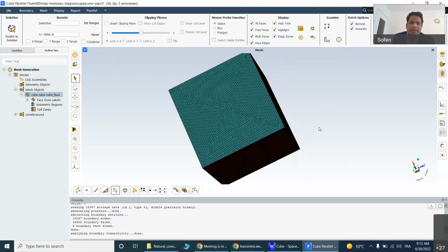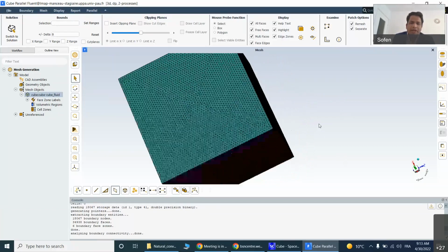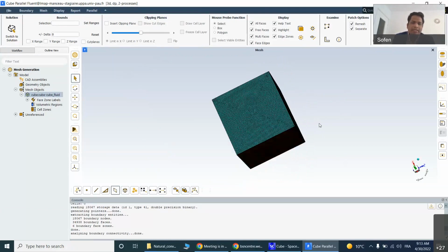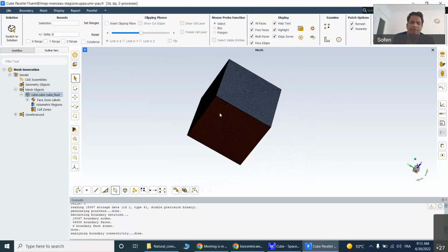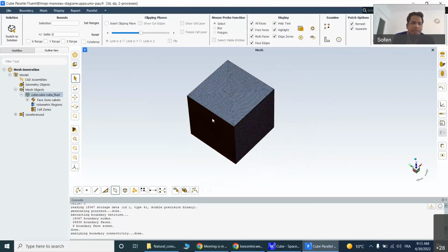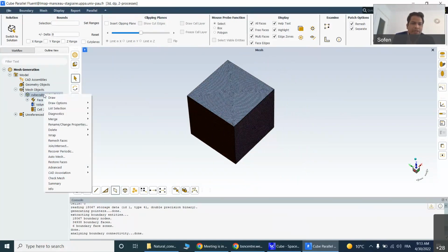To generate a volume mesh, the first thing required is a good surface mesh, right? So I just gave some rough import settings. Based on that, the surface mesh is prepared and imported to Fluent. Then you compute whether you have a single volumetric region or multiple volumetric regions. So just first check the quality of the surface mesh. If there is some free face, some opening, some leakage, all those things you can check over here, and you can also rectify them here. How to do that?